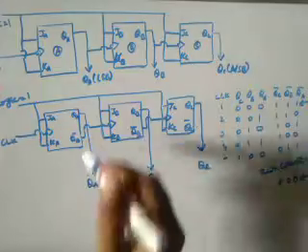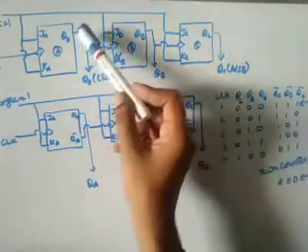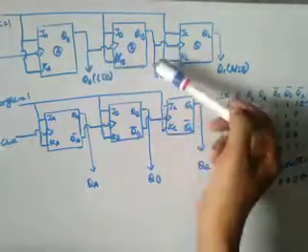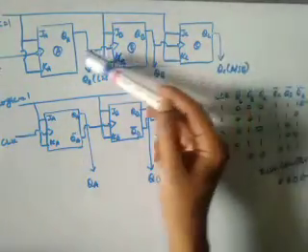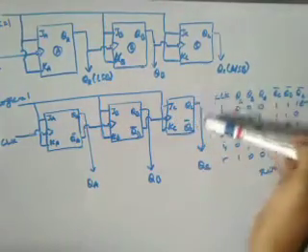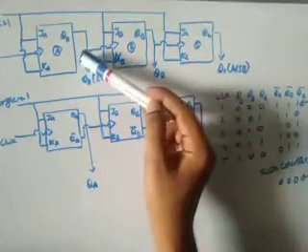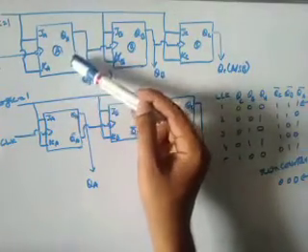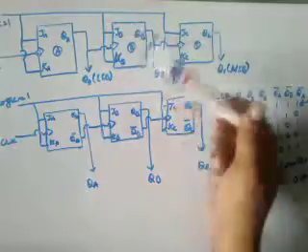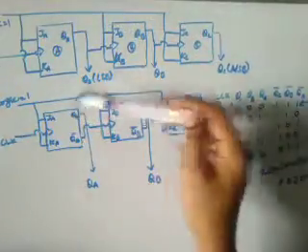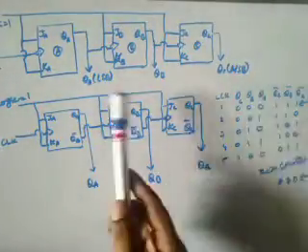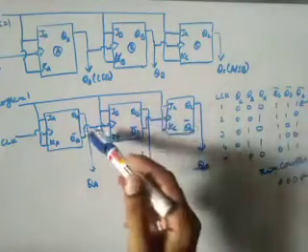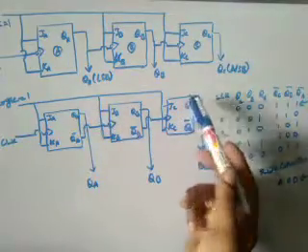Previously we interchanged the output terminals, but here we have not. We have interchanged the input of the clock, that is, we have given the complemented value. Obviously if the clock pulse is reversed, the outputs are going to change. Again we have to draw the circuit, then the clock pulses for QB and QC.